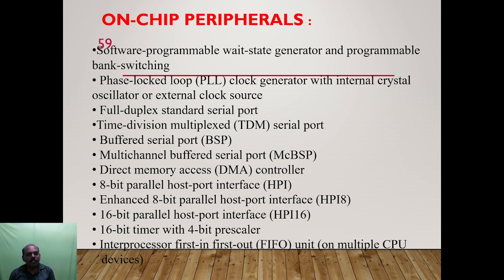Software on-chip peripherals: software programmable wait state generator and programmable bank switching, PLL clock generator with internal crystal oscillator, full duplex, time division multiplexed, buffered serial port, multi-channel buffered, direct memory access controlled, 8-bit parallel host, enhanced 8-bit parallel host port interface, 16-bit parallel host interface, 16-bit timer with 4-bit prescaler, interprocessor first in first out unit.